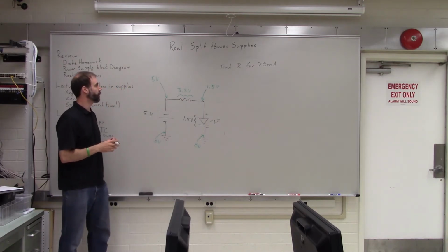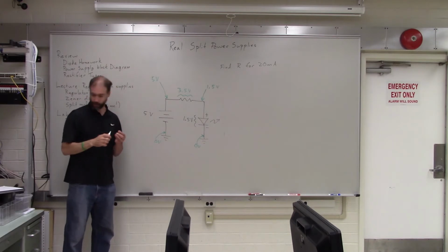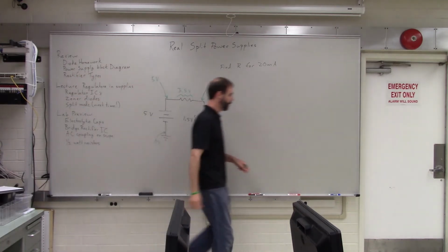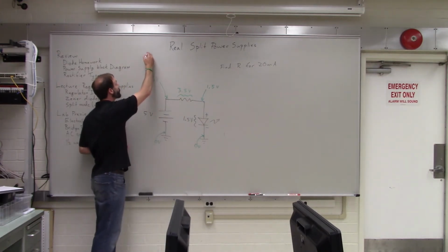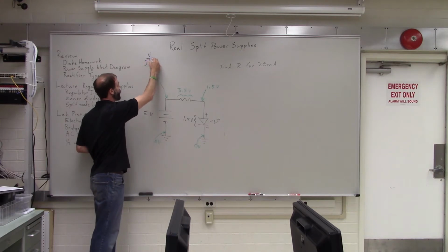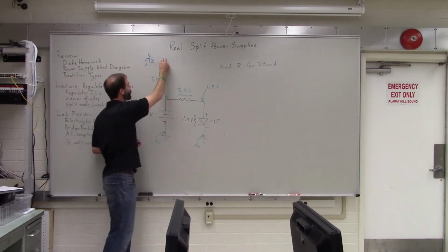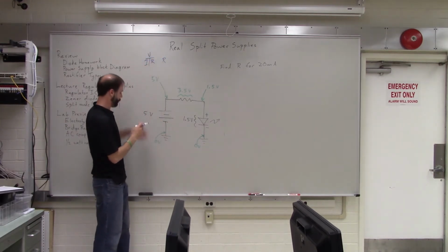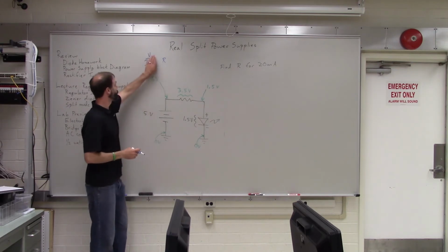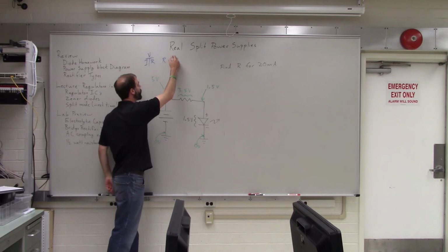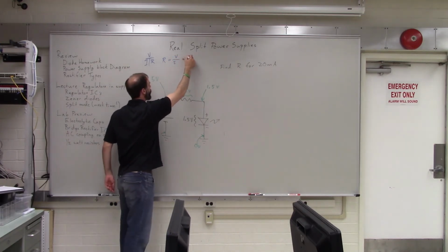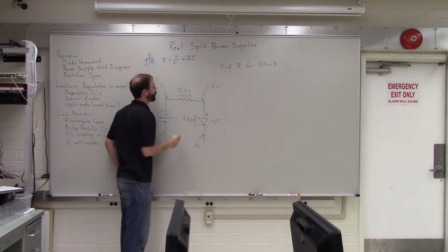Exactly. Again, we can use Ohm's law to figure out the resistance. Ohm's law is V = IR. Here we want to figure out the resistance, so we cover that up and see that it's V divided by I. So that's 5 volts divided by 20 milliamps.